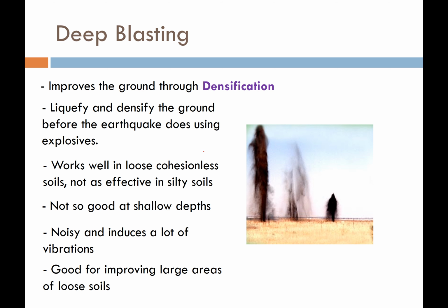And so this method can work really well if we have a loose, cohesionless soil. And the nice thing about it is explosives are super cheap. So this can be one of the most cost-efficient and effective ways. But it's not very good at shallow depths for obvious reasons. You know, this isn't a minefield. We're not trying to blow the ground up. We're just trying to densify the ground. And you can imagine that it's very noisy and definitely induces a lot of vibrations. But if you need to improve a large area that's comprised of a clean, loose, cohesionless soil that's saturated, and you want to do it in a cost-effective manner, blasting might be a good alternative.